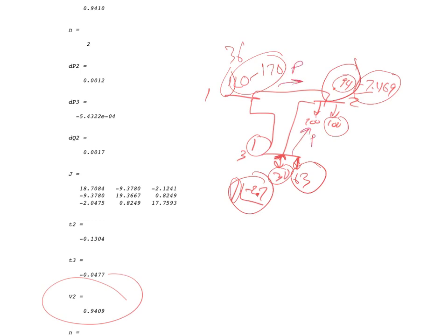Comment, question? For the angle, so the power is flowing from the larger angle to the smaller angle? Real power flows from the higher angle to the lower angle. Yep. Reactive power follows the magnitude. So if one of those buses was a positive 20-degree angle, it'd be more power than 170, right? So the question is, if the slack bus is 1 at an angle of 20, you'd have way more power coming from your slack bus.